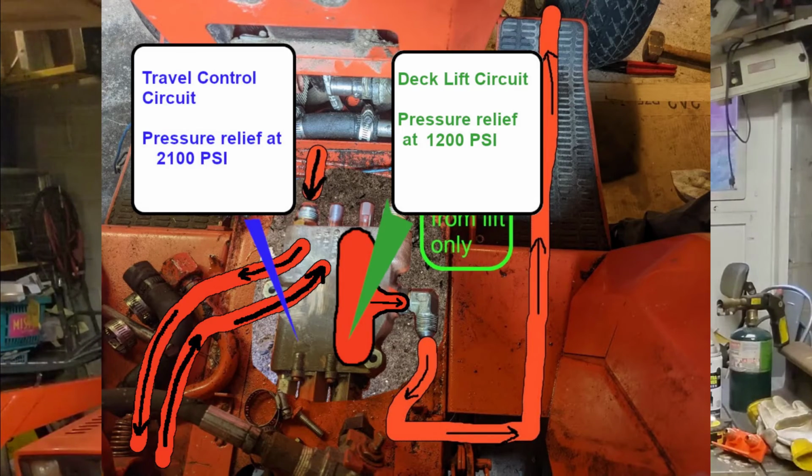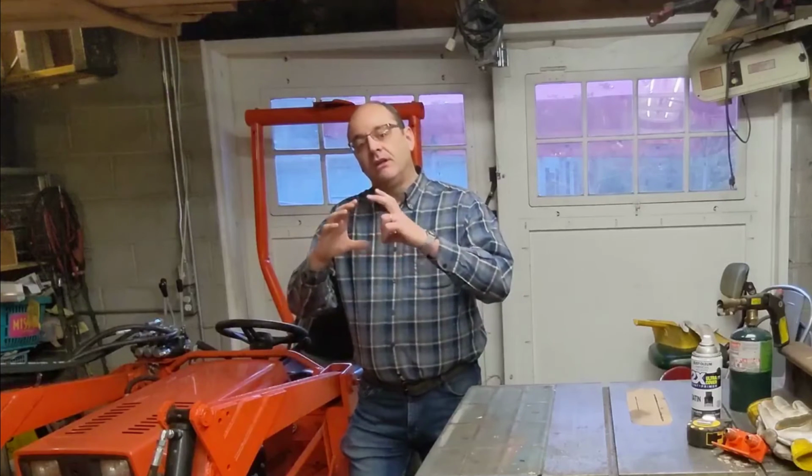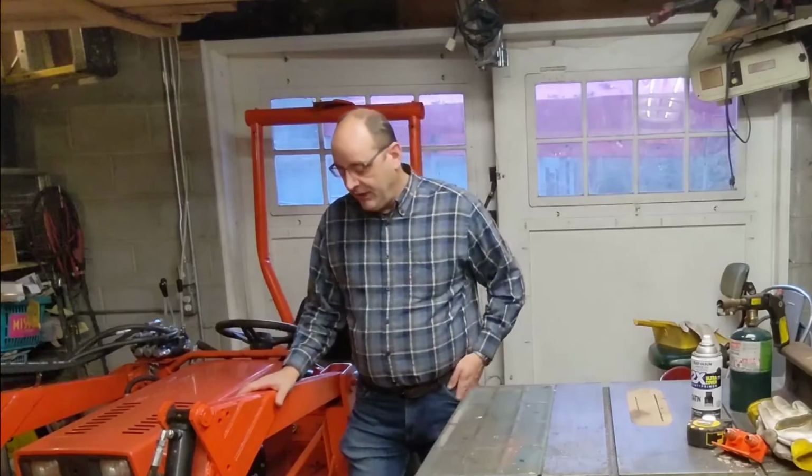Now when Case built their loader, they simply dialed up the pressure in the lift circuit to about 12 or 1400 psi, and then they designed the loader to operate on that relatively low pressure. The way they got around the lower than normal pressure is they used lift cylinders that have a larger than normal diameter. So the greater surface area of the piston inside the oversized lifting cylinders allows you to use that lower pressure and still achieve the same force that you need.